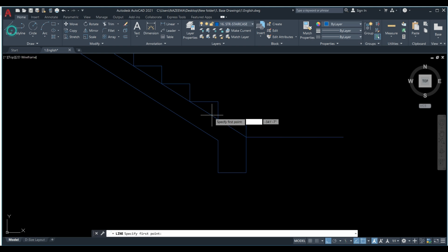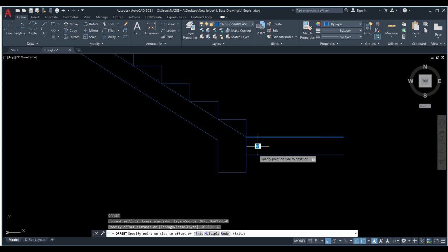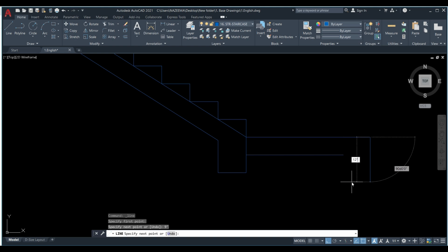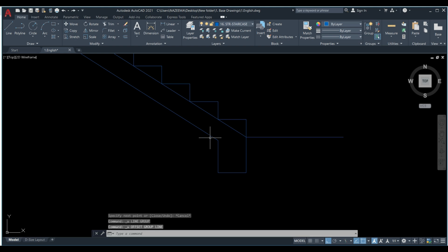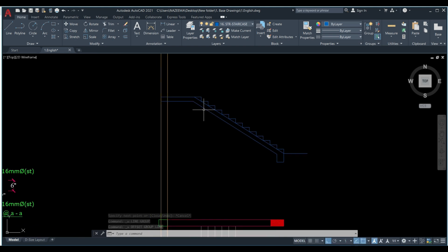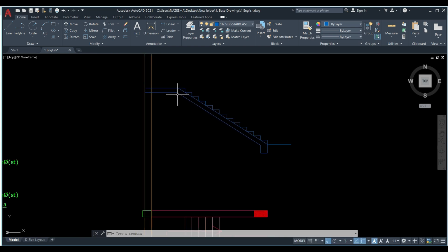you can give that. So in that case, you have to come over here and give an offset of 6 inches almost. Then from here you have to go 9 inches to get your plinth beam. Then from here we'll go 12 inches and draw it accordingly. Yeah, something like this it will come. But we have the plinth beam right over here, so we have to keep that in mind and draw it like this.